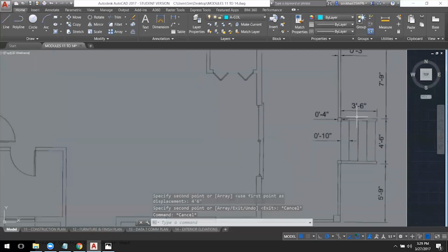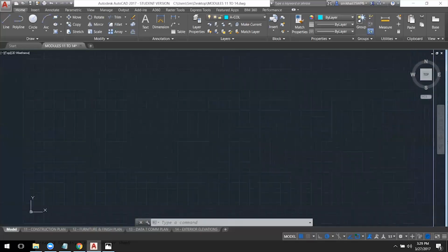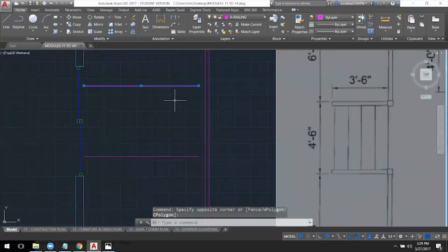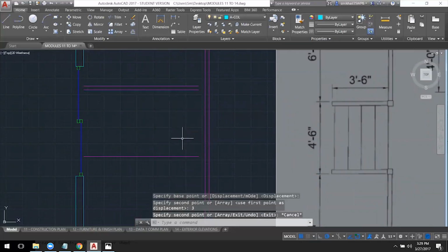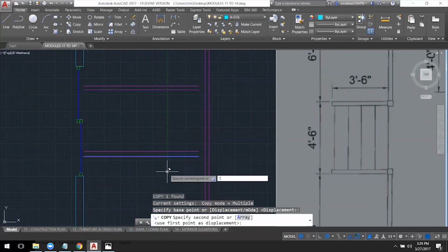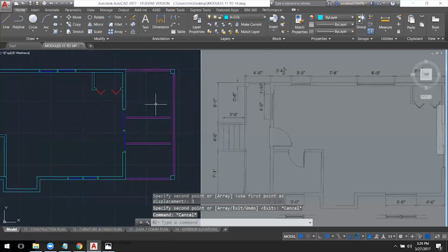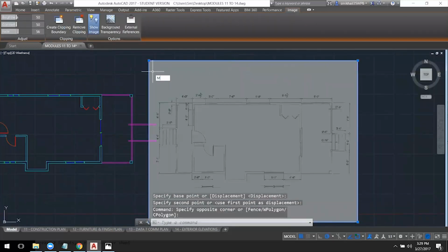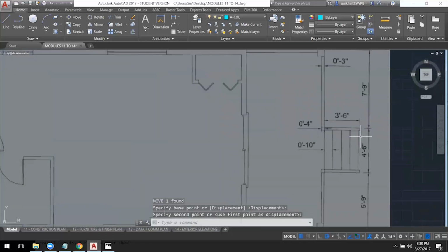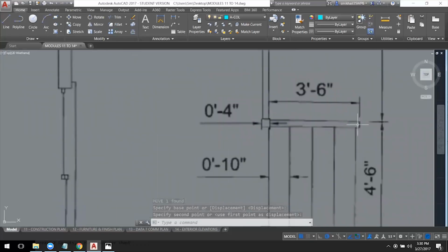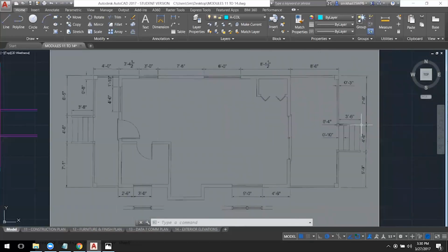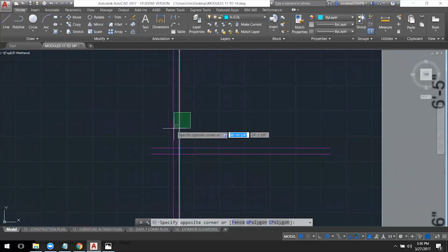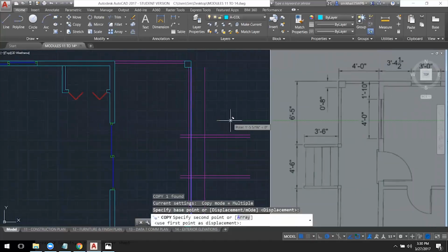And the railing is on the inside of these dimensions, 7'9" plus 3 inches here. And then after the 4'6", I'm going back up 3 inches, the thickness of the railing. So I'm going to select this one, copy it, 3 inches. And this one, copy it to be 3 inches this direction. And I can move these towards the outside of my building or my porch. The depth is 3'6". So I will copy this line, 3 feet 6 inches.